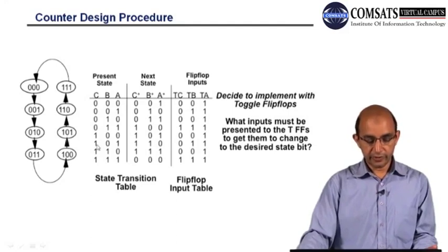Here, if you see, this 101 moved here, and the next state is 110. And this is also important: after 111, you can see that all the columns have been reset to zeros. These are the inputs for the flip-flops that have to be used.